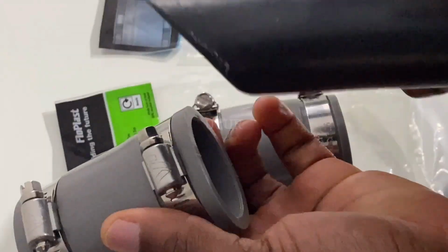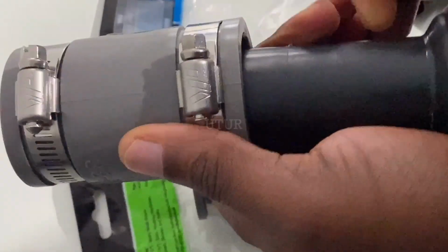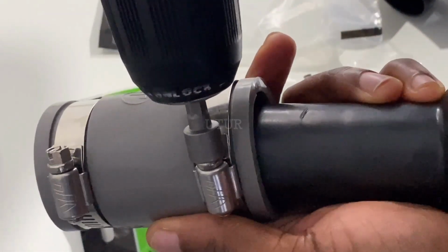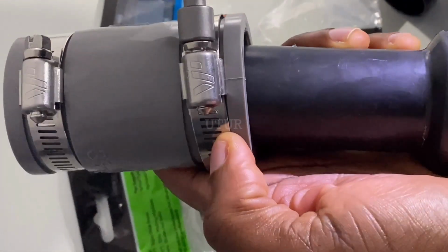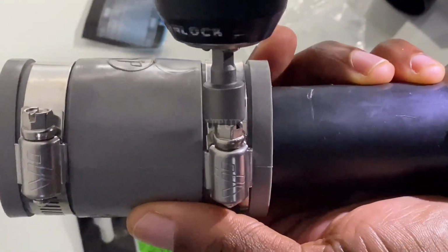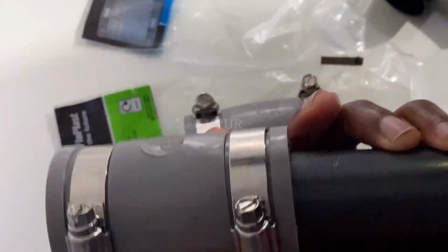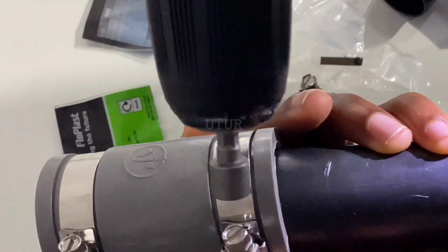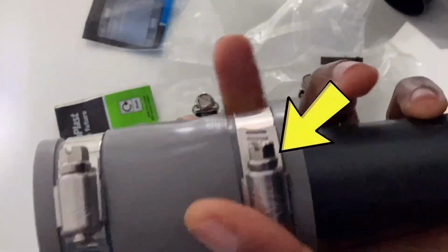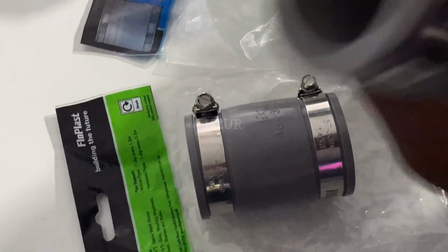The only risk associated with installing the non-flexible bit into one end of the coupling is that when you're moving the circular saw, it could break the vacuum adapter, and that's because the non-flexible bit of the vacuum hose is static, and so that could easily yank or break the vacuum adapter, which is moderately sturdy. You can see a tiny little gap between the coupling and the non-flexible black hose.